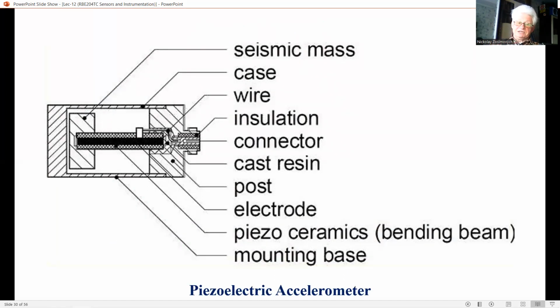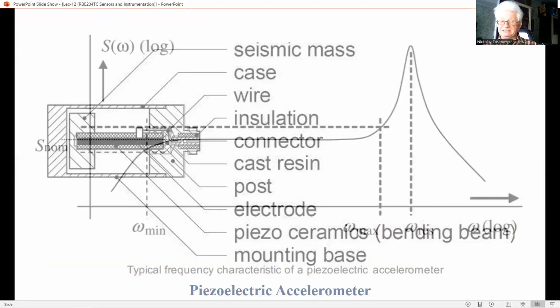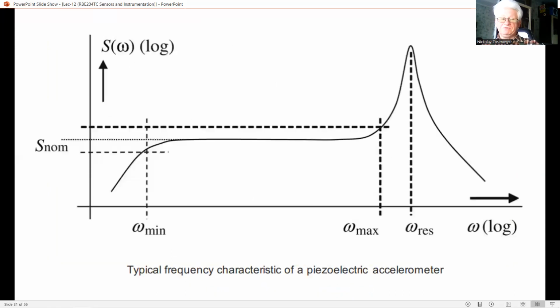An angular acceleration sensor can be created as well by a special geometric arrangement of 4 piezoelectric elements, in case of PVDF, and 2 seismic masses. An angular sensitivity of about 0.1 picocoulomb per radian per square second has been achieved by suspending a seismic mass on a sheet of PVDF.